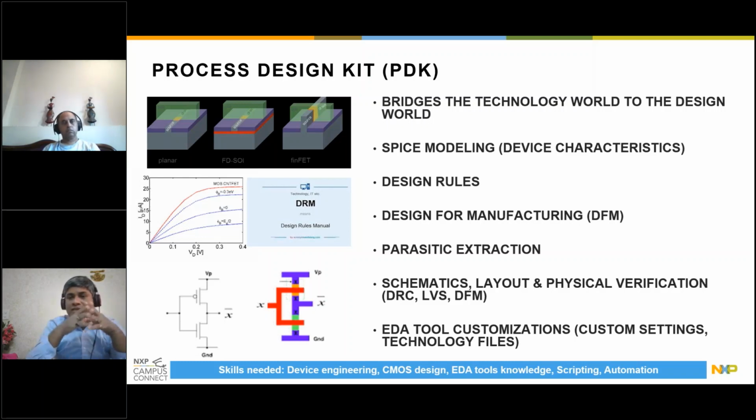Then there are EDA tools, as I said. You cannot do this on... It's very good in the good old days, we used to do it only on paper, pen and paper. But when you have to use CAD tools, then also there are various kinds of settings which come along. There's a lot of scripting which gets involved. They have to make the technology file. For example, when you translate a manufacturing recipe into a design recipe, you have to know how to codify the technology files. All this world is that of a PDK.